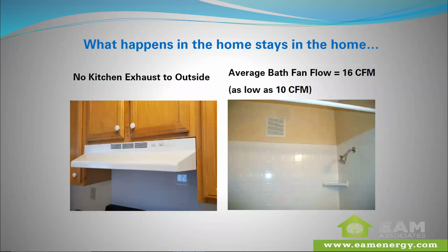Other issues in the fundamental vein. So no kitchen exhaust to the outside. They just had a recirc hood. These do not do anything for moisture control. They have, at best, a grease trap sort of filter. Moisture just goes right in and then gets blown right back out and dispersed into the apartment. And then their bathrooms were a similar problem.